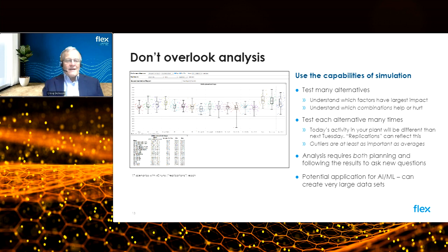The other thing I'll point out here, and this is maybe repeating a little bit what I said a minute ago, is don't overlook the analysis. In a typical simulation project, the analysis is probably at least 40% of the project time. It's not a case of, I've built the model, now I have the answer. You actually need to do the experiments. You've basically built the laboratory, now you have to use that laboratory. When you're doing that, you want to test a lot of alternatives. In fact, it's not strictly necessary for all those alternatives to even be practical. Sometimes you can learn a lot about how a system might actually operate by trying something that you know it would never be asked to do.